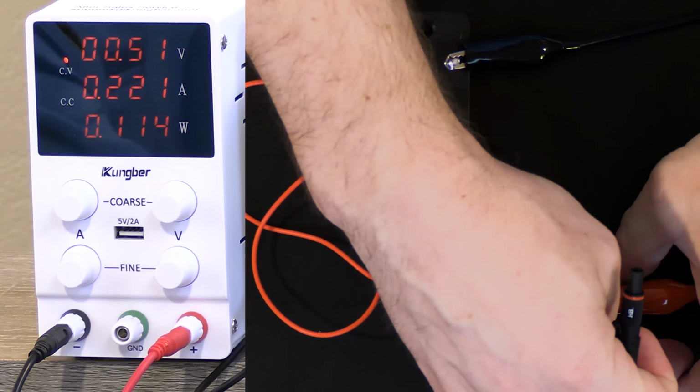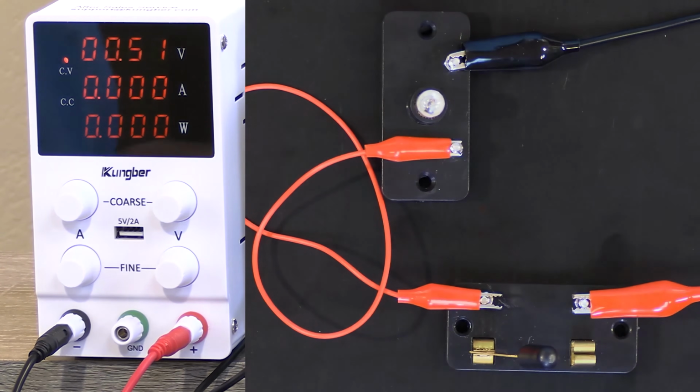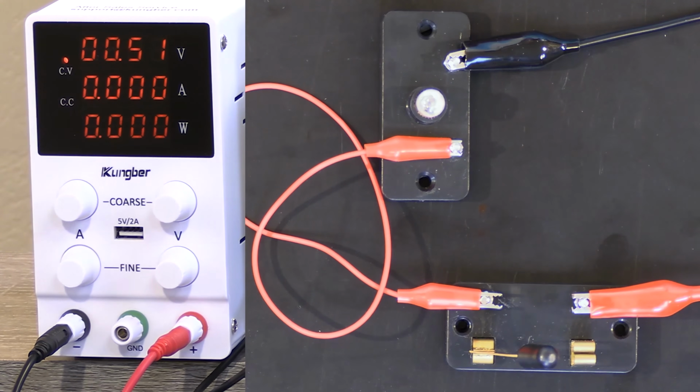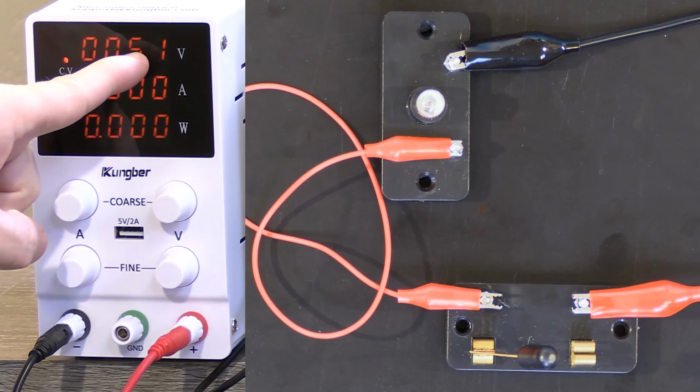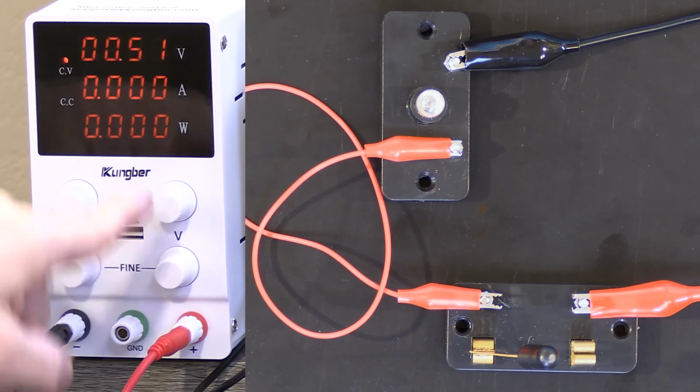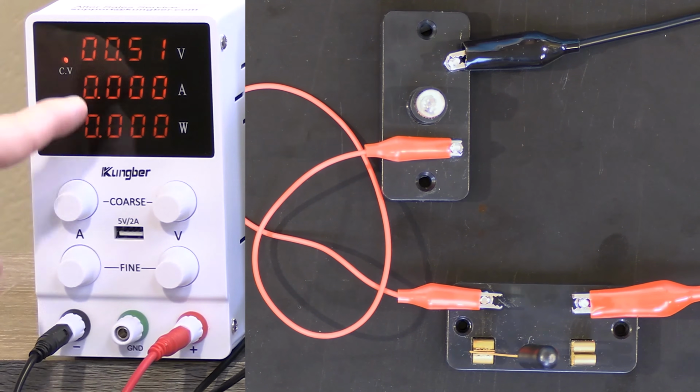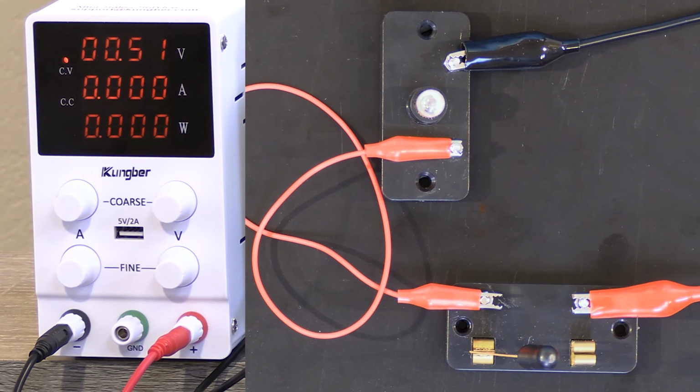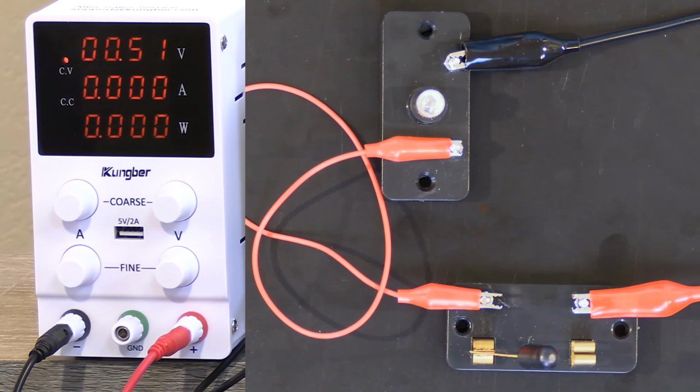But notice if I open this circuit, right, then the current goes down to 0. There's still a voltage across here. Notice the voltage is still half a volt, but there is no current. Why? Because the voltage is the push. This display is telling me how much it's trying to push, but because I've physically broken the circuit, there is no current anymore. So there can be push without flow, right?